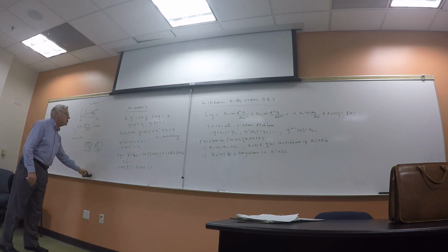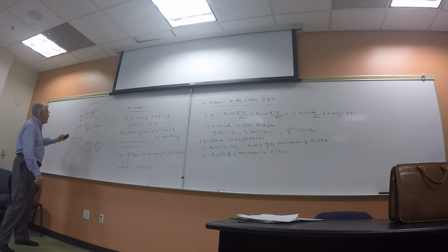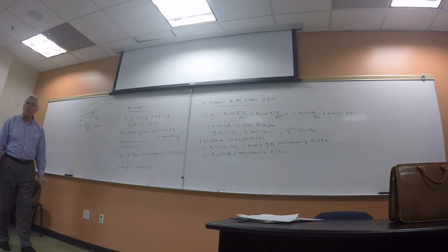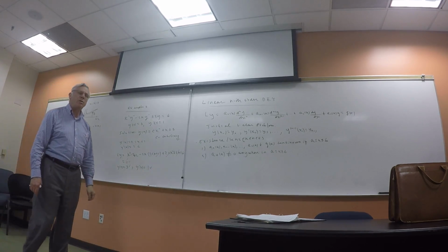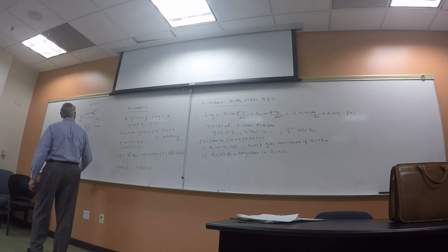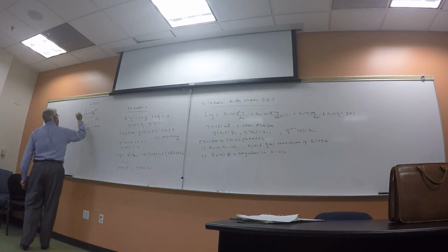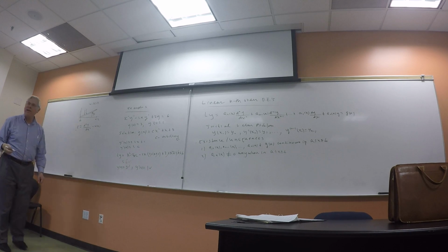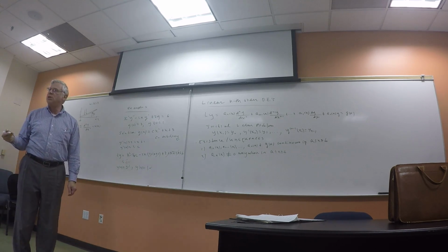Okay, so you have this equation now, okay? And what happens depends upon the supports, okay? You can support a beam in different ways. The way I drew it over here is basically clamped at 0. Imagine there's a wall over here, okay? And it's just stuck into the wall, okay? That's called the geometric boundary condition.